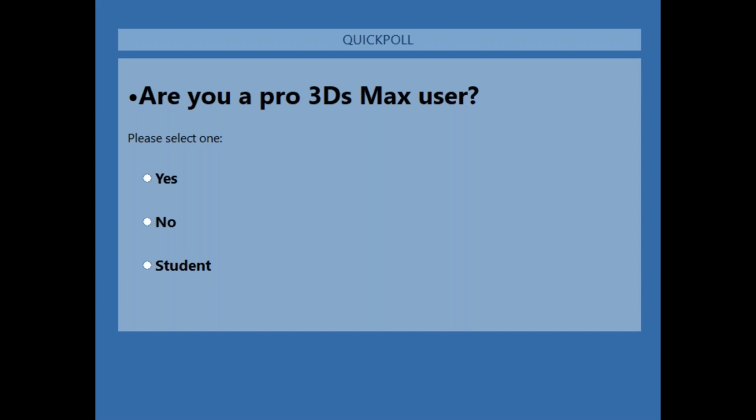Possible to create HDR image using 3ds Max by importing images. So Harish asked, is it possible to create an HDRI image using 3ds Max by importing images? Yes and no. HDRI images can be created when you export an image from any 3D application, because you can export them as an EXR file, and those EXR files will also have separate passes like normal pass, occlusion pass, beauty pass, and all these passes. Now that's where it actually came from.